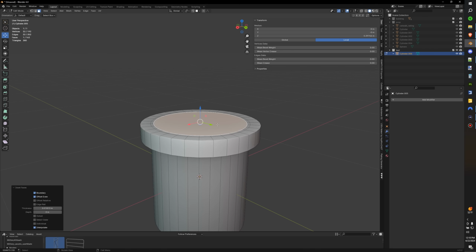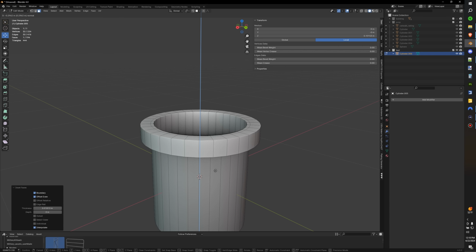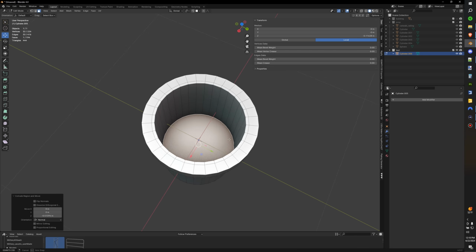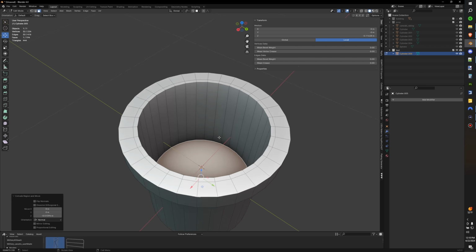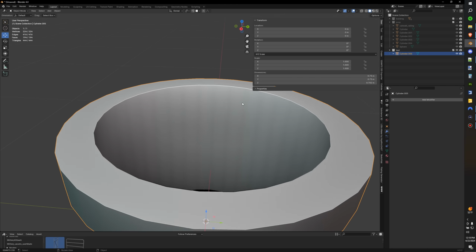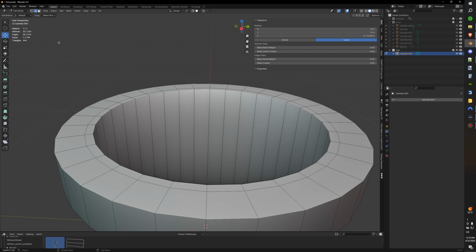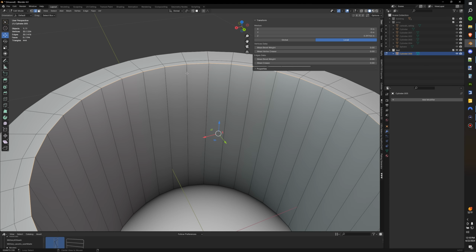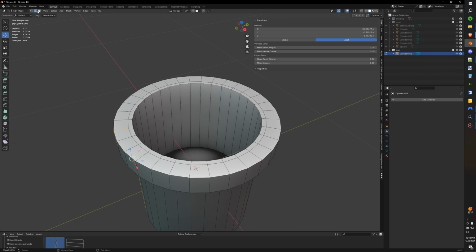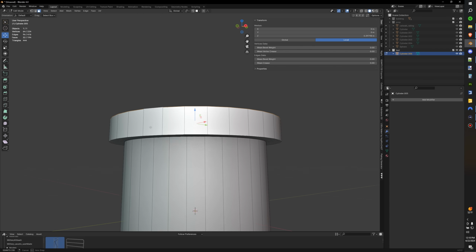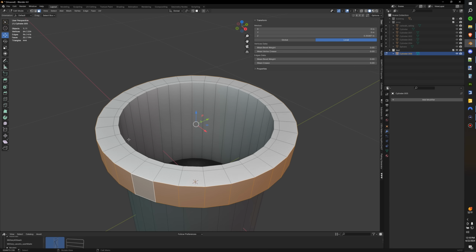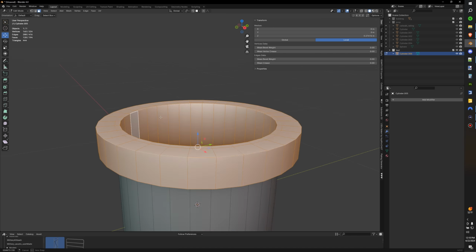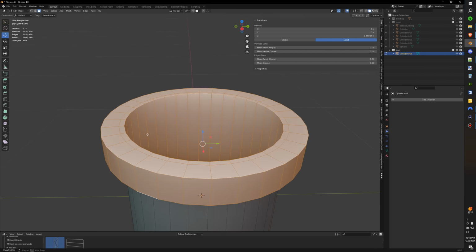Okay, now we're going to press the E button and pull down for extrude. And this is going to be the tunnel that Mario goes in, right? So now we have our tunnel here, but it's a little rigid around the corners. So what we could do is come right to this edge. We are going to hold Alt and click on an edge. If you hold Alt and click on an edge, or hold Alt and click on a face, it'll select all those faces in that. And then if you were to hold Shift and Alt, you could actually select different sections. So something like that, right?